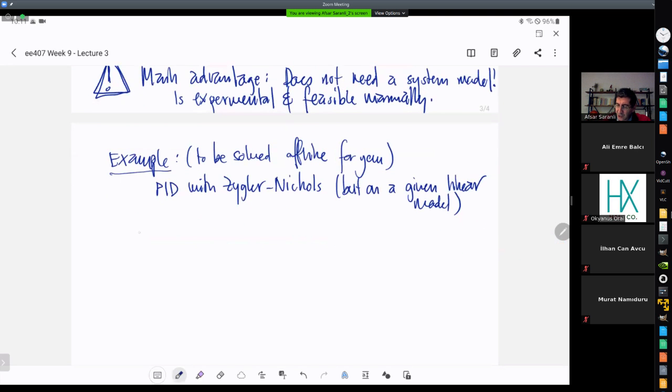I will give you this in terms of physical system components. So we will have an actuator model. Let's call this GA, and that's going to be given as 5/(2s+1). So let's say the time constants are, in this case TA is 2, and we should have some time unit here, and everything really revolves around the same time unit.